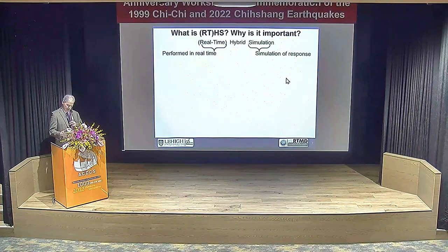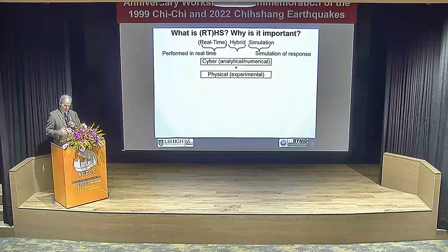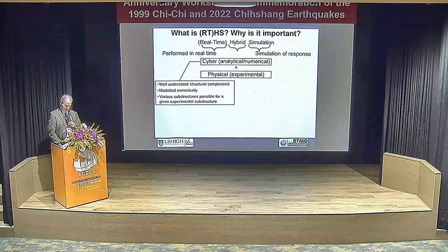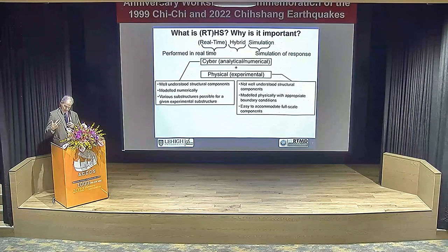So what is hybrid simulation? Well, I mentioned real-time simulation, but the word hybrid, I think if you want to attract people's attention, call it cyber-physical, because everyone outside of our realm would recognize that. Mechanical engineering, they know what cyber-physical is. So the cyber part, as I mentioned, is well understood, at least numerically, could be structural, non-structural. We model that numerically, of course, and then for a given experimental substructure, you'd have various analytical substructure models. Could be actually more than one, but I tend to lump it into one.